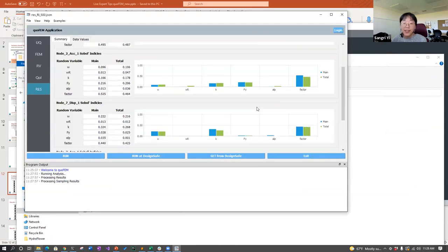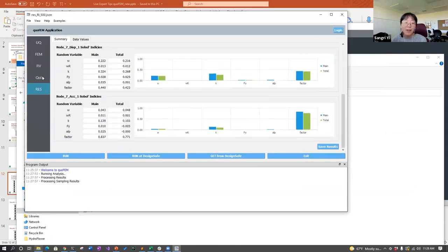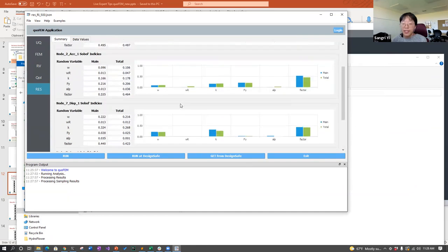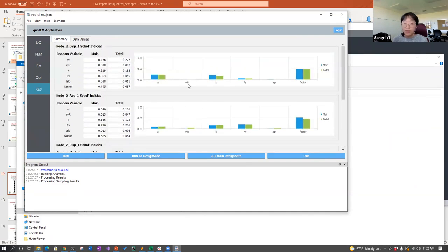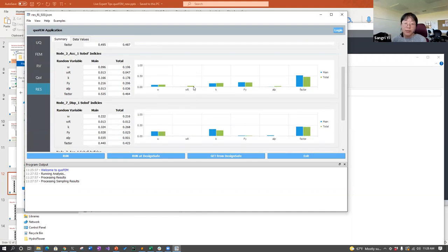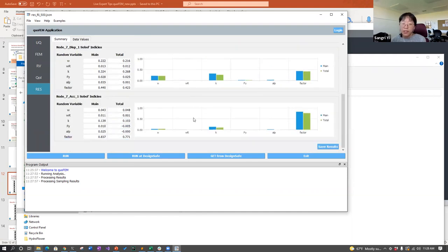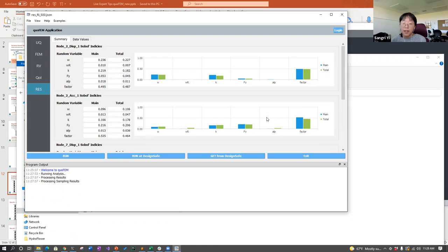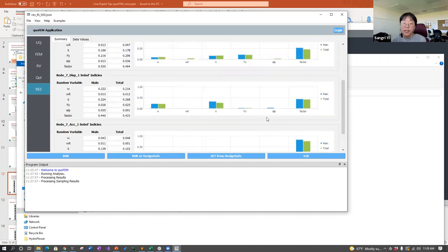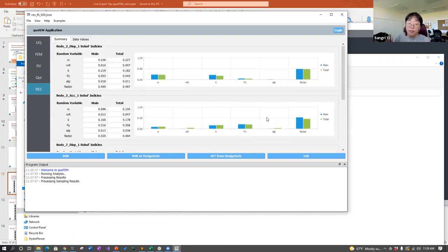Here, the first thing you can notice is that throughout the 4 quantities of interest, actually WR, the roof weight, was not really contributing much to the response. And also alpha was not really contributing. So if you need to reduce the dimension of this problem, then I would choose these 2 values to be some deterministic nominal value instead of keeping them as random variables.